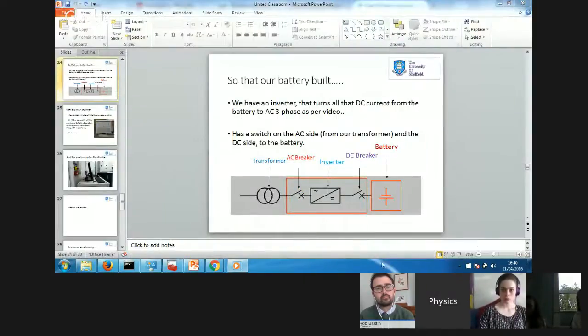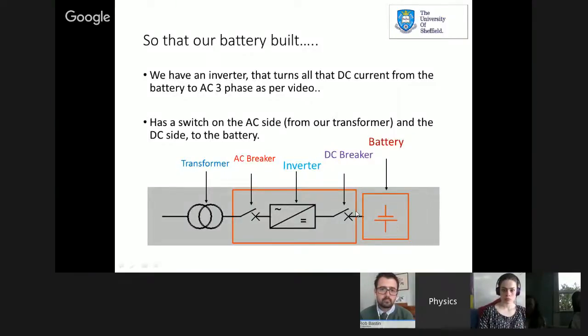So what you've got is, these are spring loaded because the power is so high. What happens is you have a motor here, and it winds up a spring, and then the spring is released, and it closes the breaker really fast. The reason is if you've got big currents and big voltages across these breakers, you've got to shut them really fast, because otherwise you get arcing, and arcing's bad because it ionizes the atmosphere and essentially turns the atmosphere into a conductor, and then you get shorts in all sorts of places. So you have to close those switches as quick as possible, and that's why they make enormous bangs.